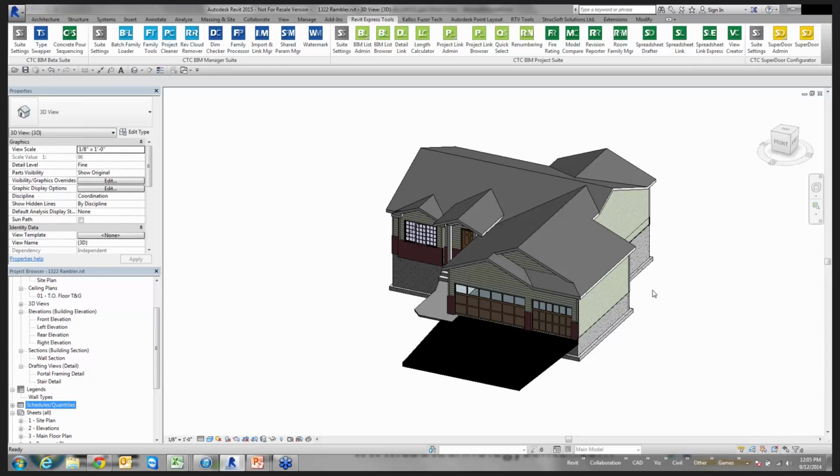So one of the things that Revit can do on its own is we can go ahead and, based off the model, extract a series of data and information based off what is drawn. For example, with walls, I can go ahead and create a wall schedule and start extracting some of that information.